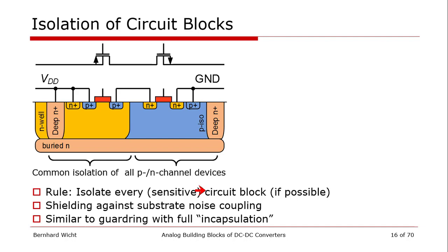To get the sensitive circuits even more protected, we can use isolation by inserting some highly doped N areas and encapsulating the sensitive analog blocks, so that gives an additional protection. I have done this for many years, these concepts, so guard ring, of course, plus isolation, and we never had any issues with coupling, which otherwise, due to the bipolars, is still quite a risk.